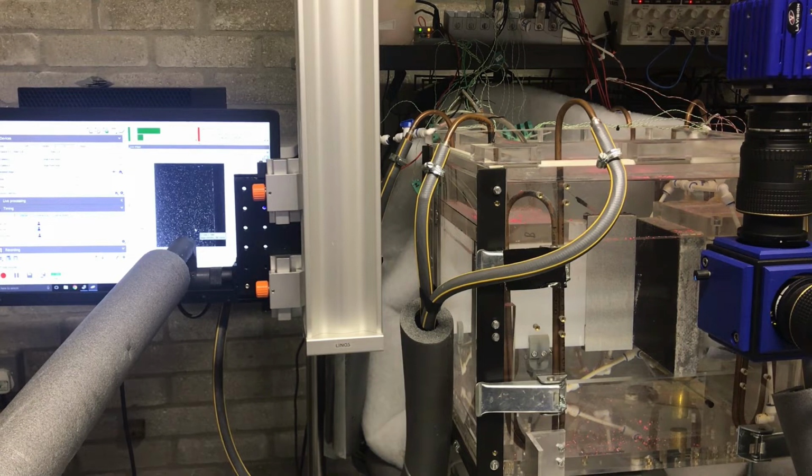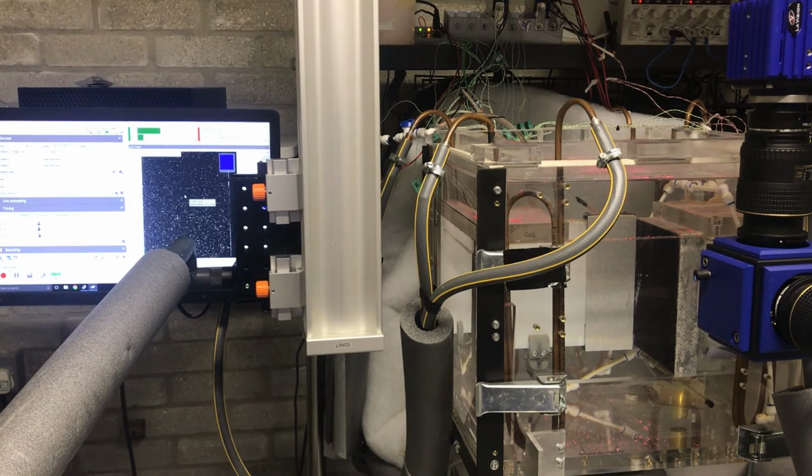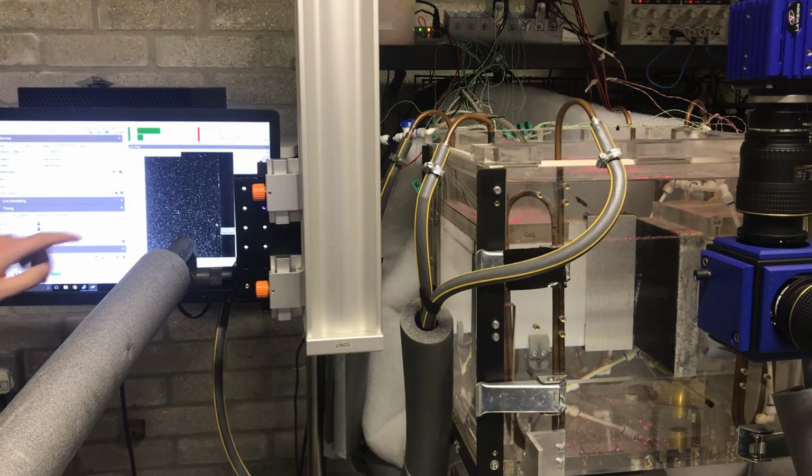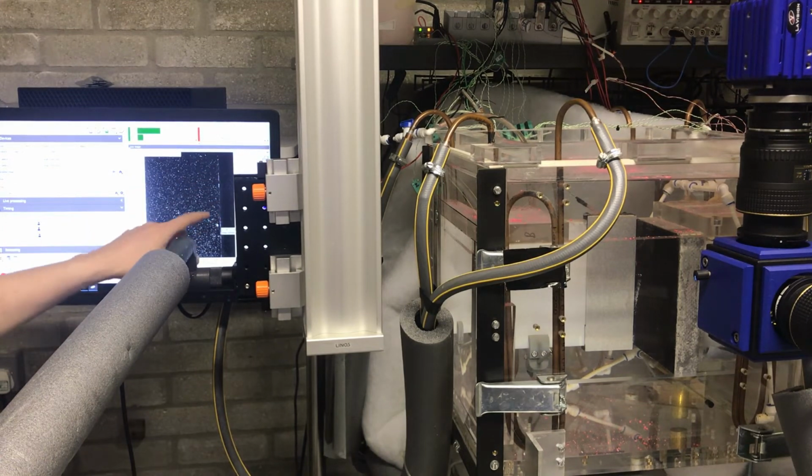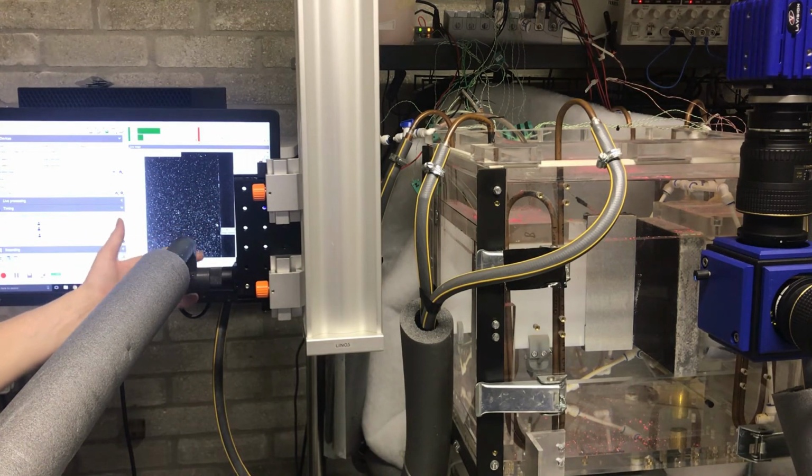Some of the hardest parts to taking the measurement are actually to do with getting appropriate seeding in the region that you want. At the minute the seeding is kind of uniform across this geometry, but as soon as we switch the heater on, what we'll see is a region near to the surface firstly becomes refracted, blurred and lost from view.